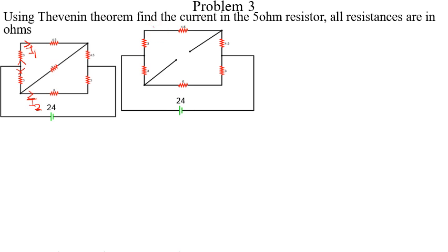The current coming here should be I1, the current coming here should be I2, because we've removed this to find VTH. Since we've removed this, when current gets to this node, it will not split. It just moves in one direction, and here they combine and come back.